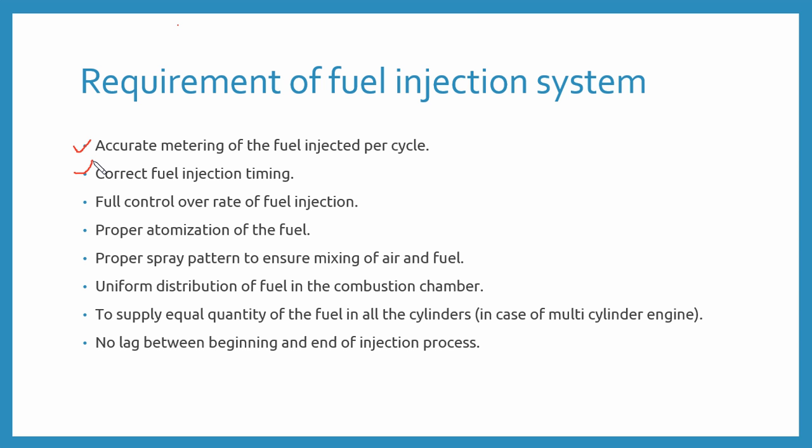We know that there are four strokes in the working principle of this CI engine: suction, compression, expansion and exhaust. The proper time for injection is just before the end of the compression stroke to just the start of the expansion stroke, in between.